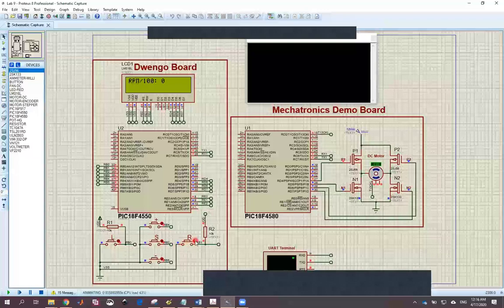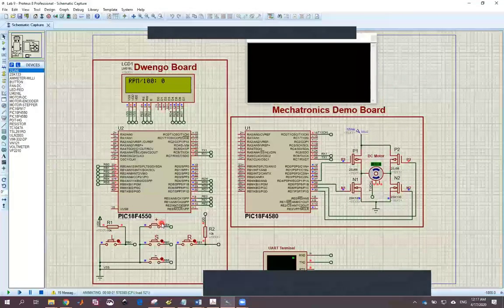Okay, so let me press R. It configures the motor in the reverse and forward mode, or the right direction, and we can increase the duty cycle. The duty cycle increases very slowly because it's only plus 10. So I'm incrementing it by 10. You can increment it by 50, for example, to make it faster. And you can see the motor is rotating slightly towards right. It's very slow, so you have to keep on increasing the duty cycle to make it faster.